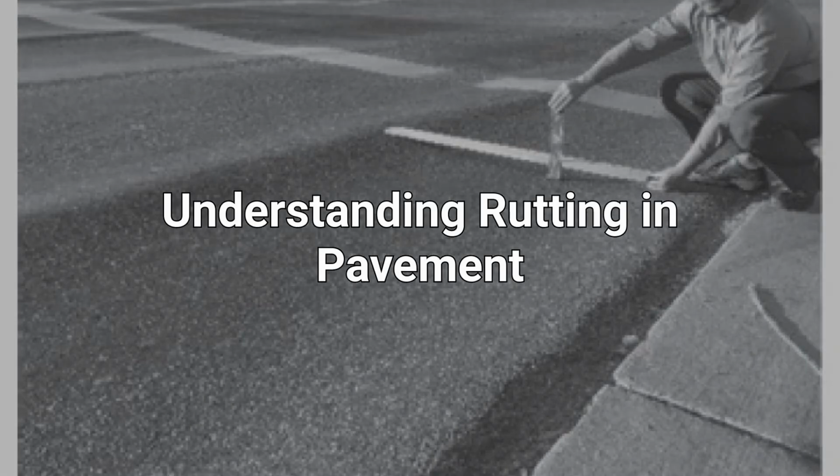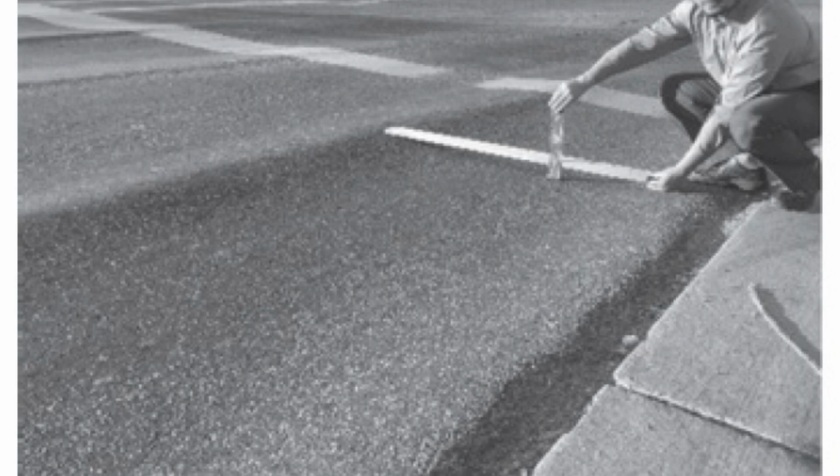Understanding rutting in pavement. Rutting is the longitudinal surface depression in the wheel path resulting from permanent deformation in each pavement layer along the wheel path, AASHTO 2015. Ruts are particularly evident after a rain when they are filled with water. The rut depth is the vertical difference in elevation between the transverse profile of the surface and a wire line across the lane width, as shown in the figure. As the rut depth increases, the amount of water ponded along the wheel paths increases. It causes a reduction of surface friction and increase of hydroplaning.